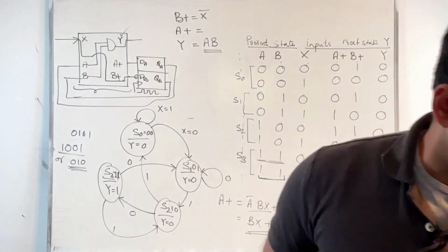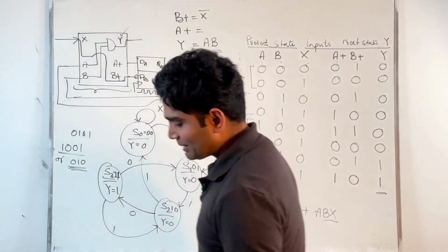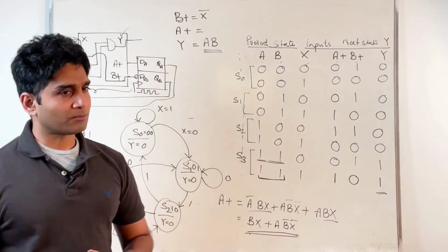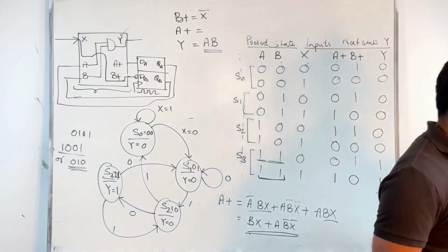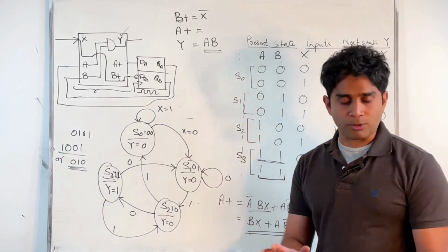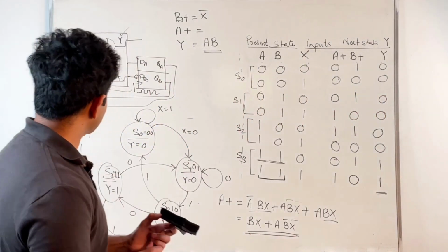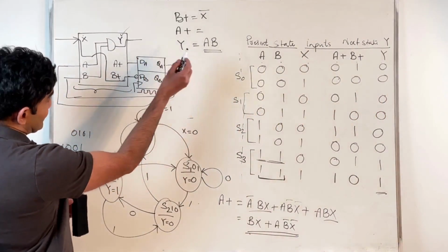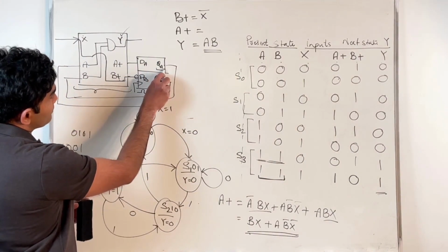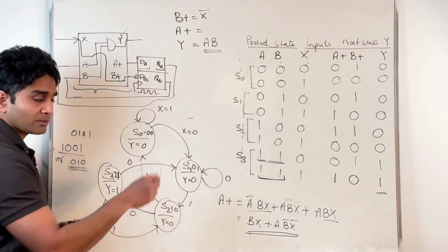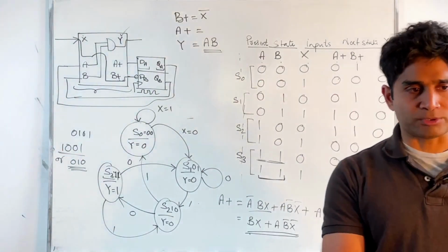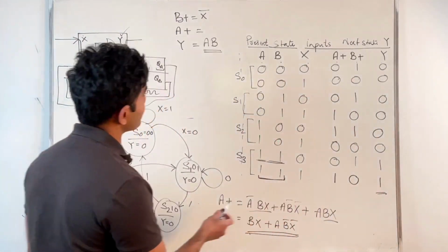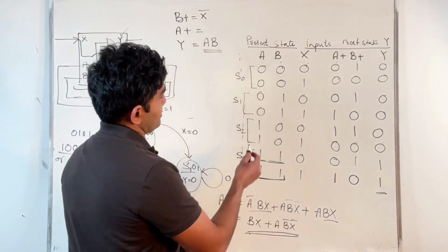Now, as I mentioned before, I can implement a state machine. In all the implementation examples that we have taken so far, we have used a D flip-flop. Again, the characteristic of a D flip-flop is that the output follows the input. With each new clock transition, the output follows the input. And that's why we really did not have to do anything extra here.